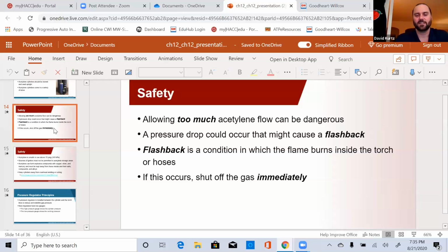If you get nervous or get excited and you don't realize the needle valves, the best thing you do is set the torch down, put it in the grating, go to your manifold valves, and turn it off there. We want to isolate the flow of gas when this flashback occurs. If you have it in that constant state, those flashback arresters, they're only rated for a certain temperature and it could ruin them. So we want to make sure anytime that we have a backfire, flashback, anything like that, we want to turn the gas off immediately.